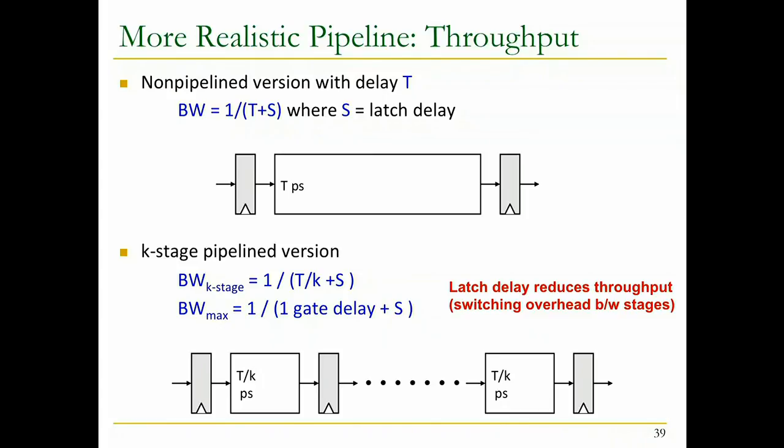And what is worse is, it's not just that, because you cannot uniformly divide. This is the uniformly partitionable sub-operations. Let's say K is 20 stages. It's not that this will take T over 20 picoseconds. You'd be very happy if it does. It usually takes longer than that, actually. So let's say this takes T over 15 picoseconds. Now, instead, you multiply that by 20, so you have 20T divided by 15.